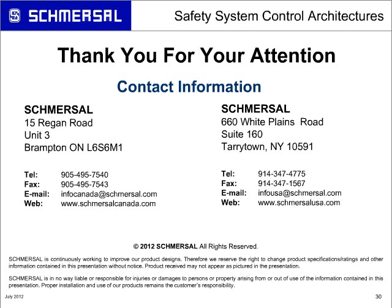Is there ways that you can achieve category 4 easier than it has been years ago? Yes, with the onslaught of electronic devices, you get more diagnostic capability, you get more wiring and daisy chaining capability to a single, simple little safety monitoring relay, and interface that with safety on drives and things like that. It's possible where you can minimize your costs and get more features, but you can definitely get out of control quick if you're trying to retrofit machines and put all this control category 4 without doing a full evaluation and determine what levels each function needs to be at.